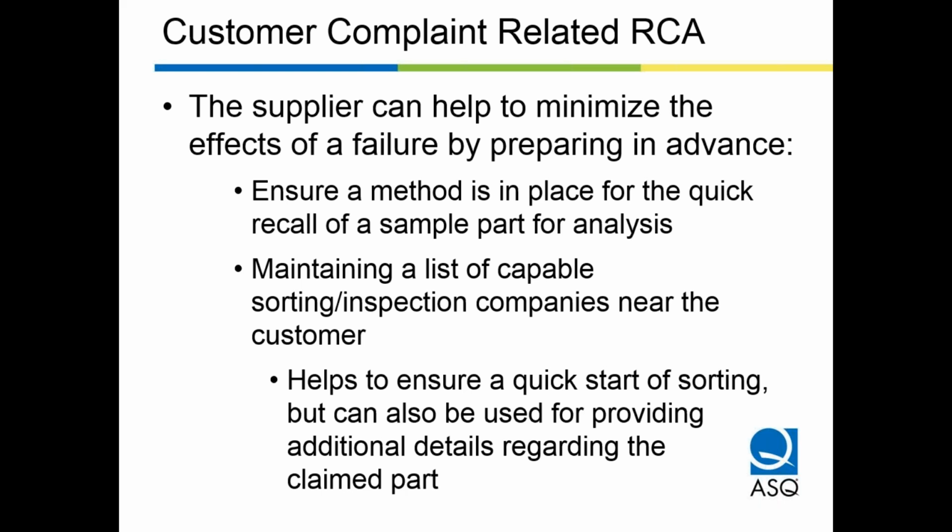Sample parts. I'm talking about empirical evidence. Give your supplier that sample part. It's critical for analyzing the issue. Additional information, if it's available: what conditions did the part fail under? Did it fail when it was pulled out of the box? That is not the same as it being assembled, in use for 2 weeks, and then returned and failed. The root cause is probably going to be different. They need this information. However, the supplier does have an obligation to ask if it's not made available.